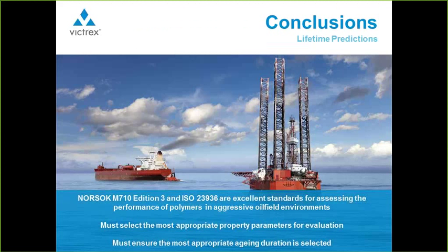So finishing up now, a few conclusions from my side. I would say that NORSOK and the ISO standards are all excellent standards for assessing performance of polymers. However, care needs to be taken to select the most appropriate property parameters for evaluation, rather than just defaulting to the norm, and the lifetime for one property might significantly differ from another.